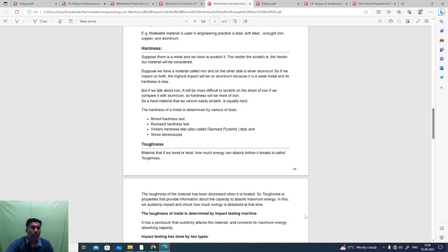For example, we are manufacturing a gear. First we proceed with the machining processes: turning, then drilling, and then thread cutting. These processes are completed. After that we send the material for the heat treatment process. After completing heat treatment, it comes to the cylindrical grinding process.